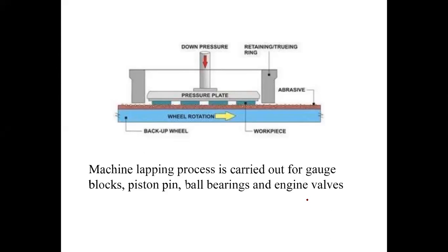On one side you have compression and combustion taking place. If you don't have a smooth surface finish, the piston and cylinder are not exactly contacting, and the compressed gases may leak through the piston and cylinder gap clearance. That is not permissible in an IC engine.